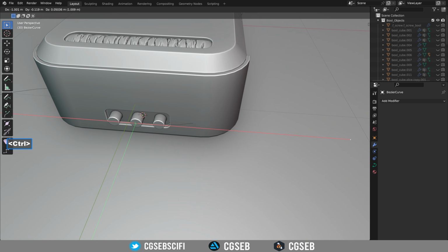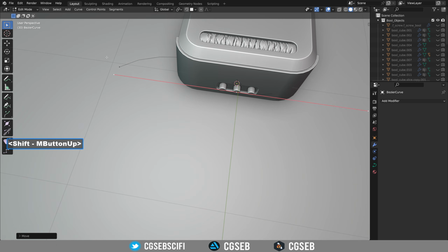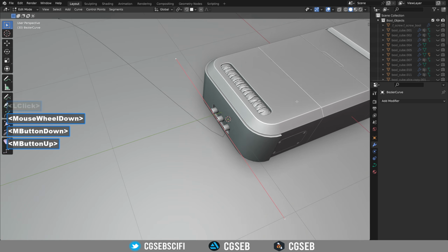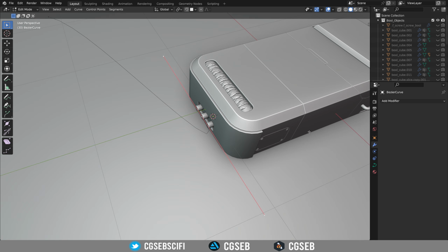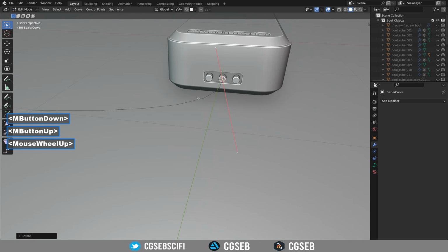So let's make it on the middle one, and then we're gonna move this point by pressing G and Shift Z, move it over there, and we need to rotate this. So R, Z, rotate, make it turn around like so.